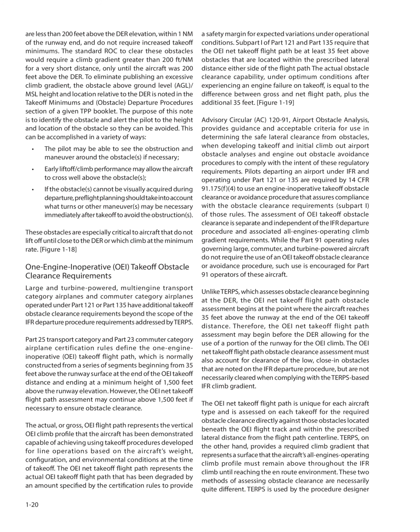The actual, or gross, OEI flight path represents the vertical OEI climb profile that the aircraft has been demonstrated capable of achieving using takeoff procedures developed for line operations based on the aircraft's weight, configuration, and environmental conditions at the time of takeoff. The OEI net takeoff flight path represents the actual OEI takeoff flight path that has been degraded by an amount specified by the certification rules to provide a safety margin for expected variations under operational conditions.